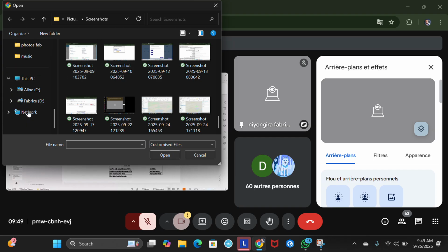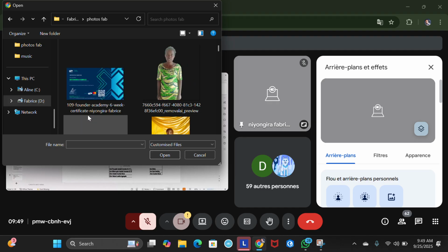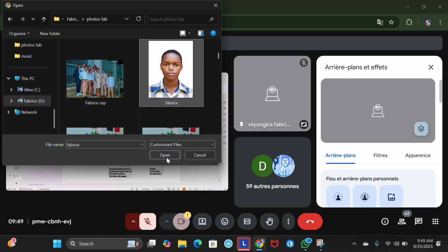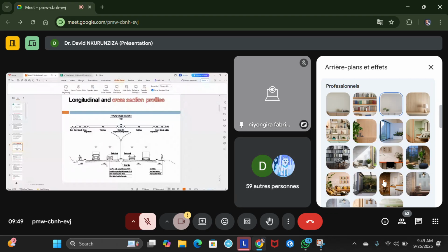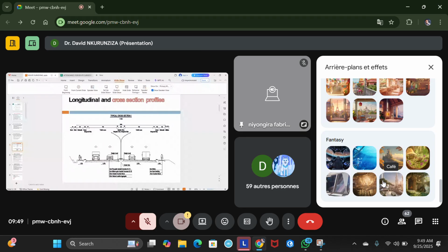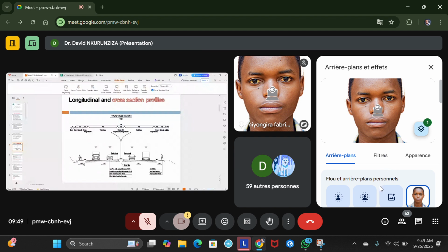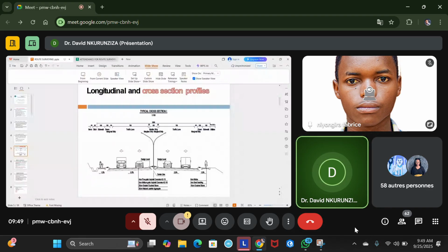As you can see, on a cross-section profile there is a lot of information. Generally, we can have information about the sloping. For example, here you can see this lane is sloping by 2.5%. This is for drainage purposes. Even this walkway is sloping by 1.5%, meaning that water can continue on the carriageway and then reach this ditch. We also have other elements that you are going to see later on.